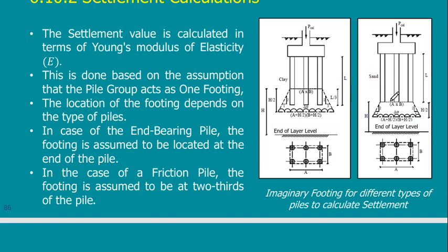Of course they will settle. How to calculate this? There is an approximate way. The approximate way is to remove the piles and put a raft at the bottom here instead of them, as if it were a foundation, a big isolated footing at the bottom.